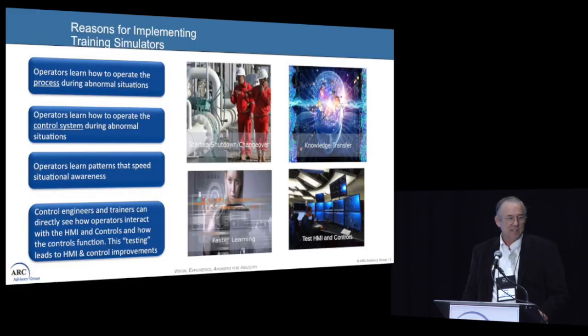So for people that weren't there, it could be 9 years; maybe they never experienced any startups, so they didn't have any actual plant experience. Now that's much different in a pharmaceutical batch process, where they are starting up, building a batch every time. These people become very familiar with the startup procedure because they practice it. There's no choice then but to use some kind of training simulator so they can practice startups.